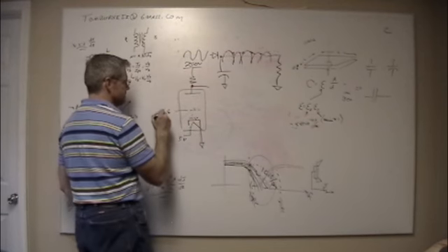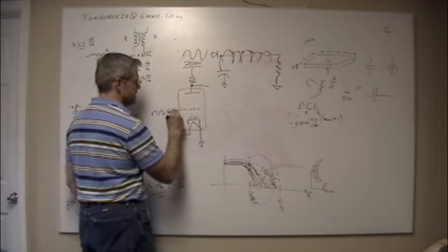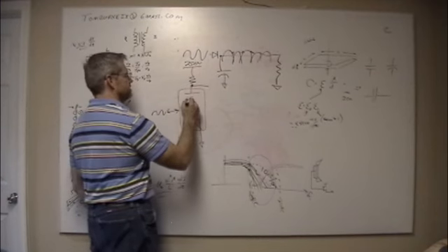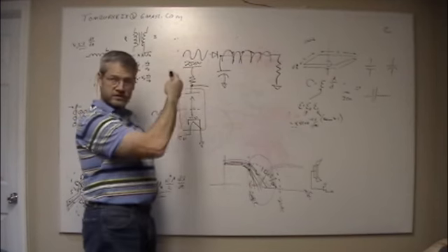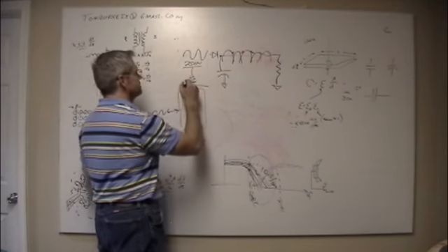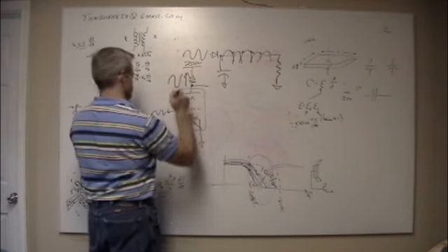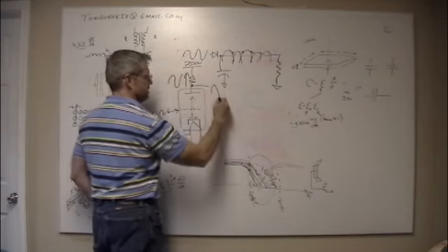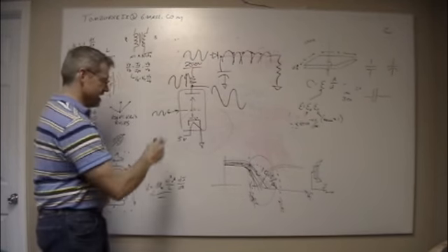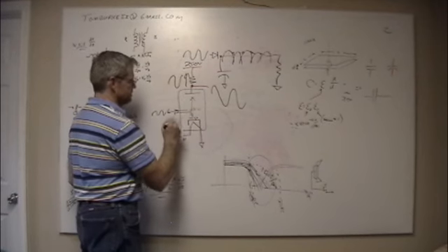And as the signal goes in here, your audio sine wave goes in here. As it goes positive, it accelerates the electrons through, and as it goes negative, it repels the electrons. So what you see here in your current, as this goes positive, the current goes with this, and this voltage here goes with this. So you notice they're in phase also. And on a tube, you get what's called a grid leak. Some of the current goes out the grid.